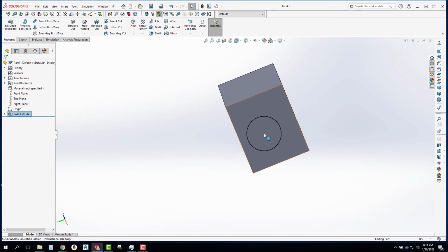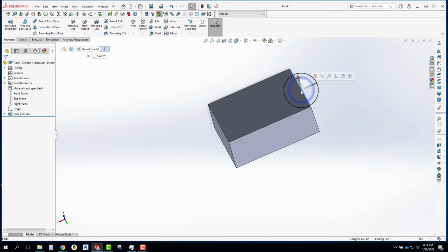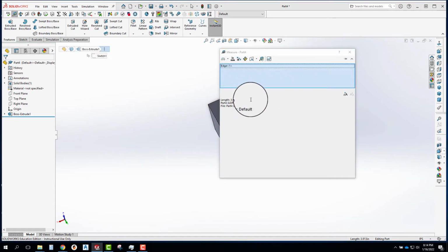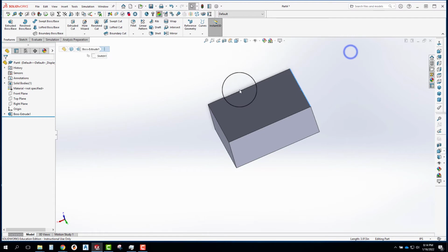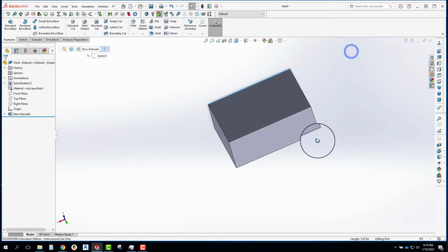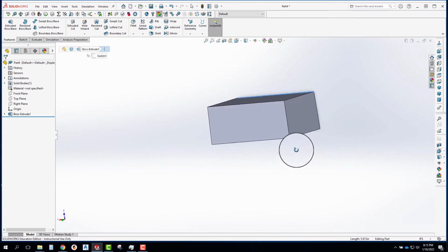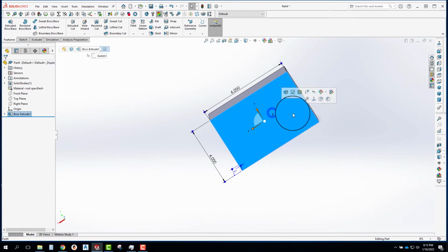So I could have had one sketch that had this size rectangle of 4 by 6 on the bottom, and then a different rectangle at the other end that is, you can see, 3.913 inches by 5.913 inches. That's what the amount of taper ended up being at 1 degree over 1.5 inches. And you could do the same thing on an extruded cut.